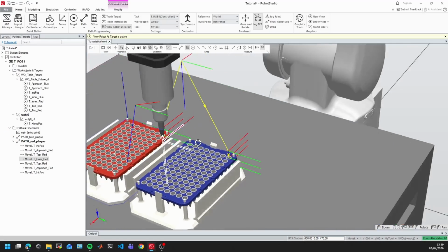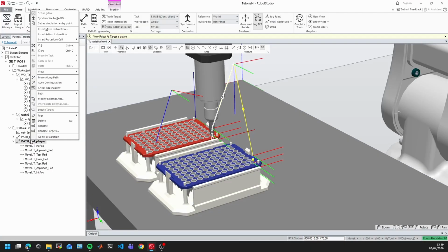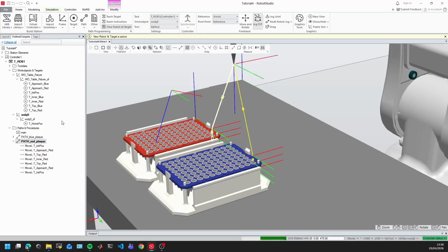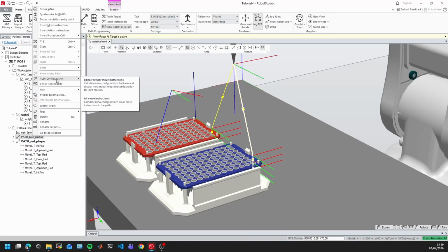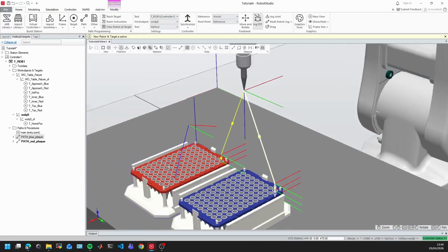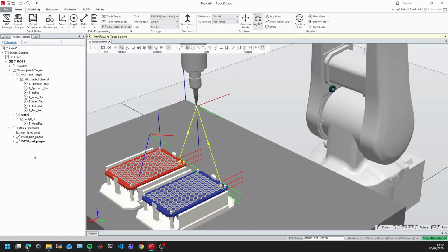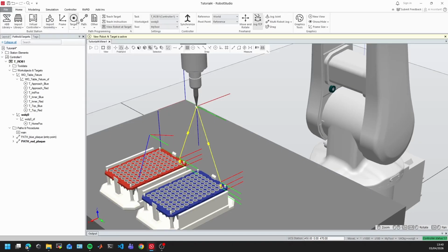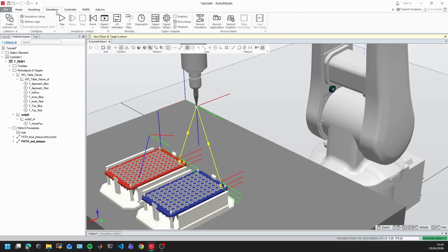So now everything is changed here, and I can check, for example, move along the path. There you go. You can see it's moving along that path, and then move along the other path if we want. Because I moved into the red one, but I can also move into the blue path. Move along the path. And there you go. So I have two paths already done. I can define an entry point if I want. For example, this one, I can just make it set simulation entry point. And when I do the simulation, if I press play, it's going to do this process.